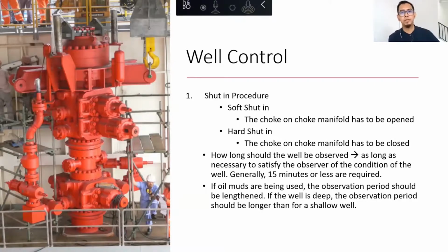So that's the intention. There are 2 types of shut-in. I know it's a bit too technical. There's a soft shut-in, and there's a hard shut-in. The difference is only the choke position. The choke position in the soft shut-in is in the open position. Hard shut-in is in the closed position.